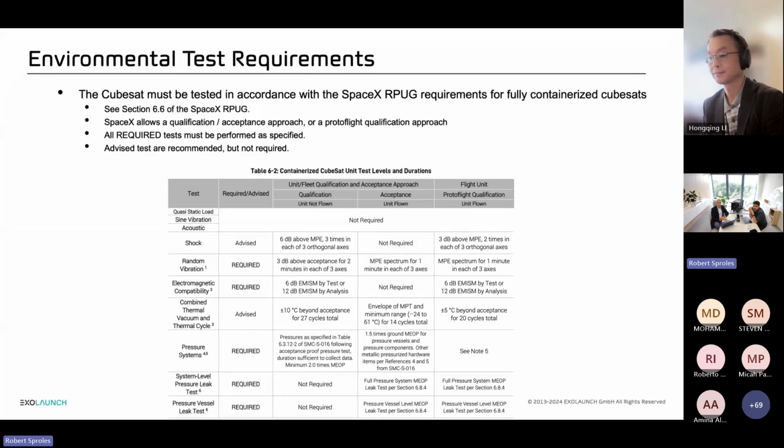If you want to verify the electromagnetic compatibility test at the same time, all you have to do is show that your satellite does not turn on during launch. The easiest way to demonstrate this is to put your satellite into a test pod, something that has representative interfaces, and we can provide a test pod for you, so that your satellite is off, but is able to turn on. It's not turning on because there's a switch on your satellite which prevents it from turning on, and that switch is pressed by the test pod.